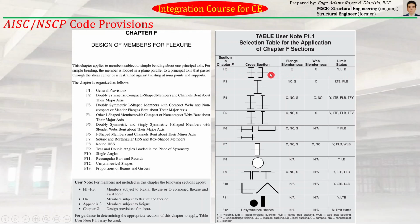So commonly, this is your guide. Actually, this table is your guide to know which particular chapter F you need to refer to for a particular section. If your flange and web are compact, go to F2. If your flange is non-compact or slender, as well as your web is compact, go to F3.